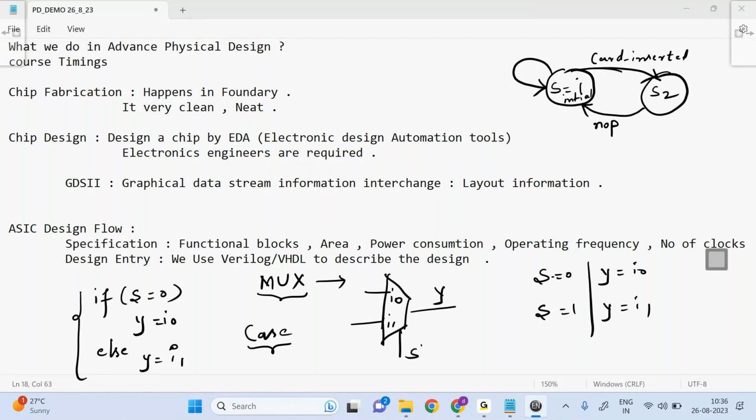In S2, what does the state have to do? It will ask for the pin. That is what the state has to do. If the pin is entered and the pin is correct, go to the next state, state 3, for a correct pin.